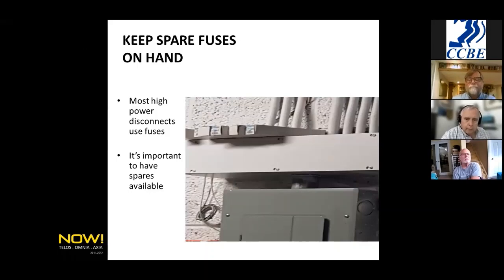Important for you to keep spare fuses on hand. One of the things that I would do on a yearly basis was do a fuse inventory of all of the fuses that were in my site, whether they are the small little fuses that go into individual pieces of equipment, or the larger fuses that went into the disconnects for things like transmitters and air conditioners. It's really important to have spares available, and here's why.